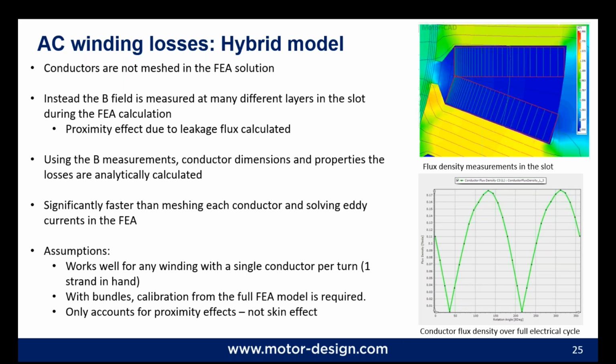And using that profile of the flux density in the slot over the operation, we use that with an analytical equation to calculate the eddy currents in the conductors. And this gives us a much faster solution than the full FEA, and in a lot of cases, very similar accuracy. So this is very good for windings where we've got a single conductor per turn, so most concentrated windings or hairpin windings.